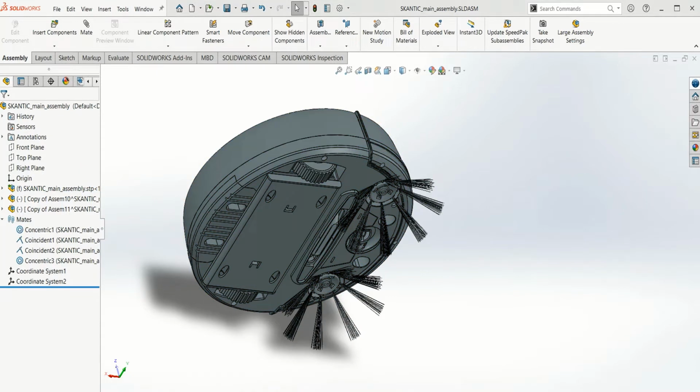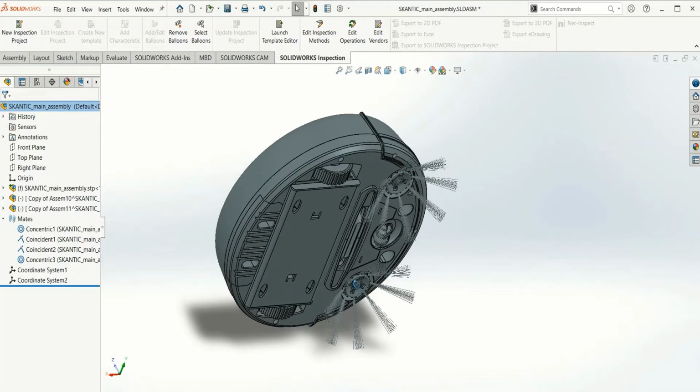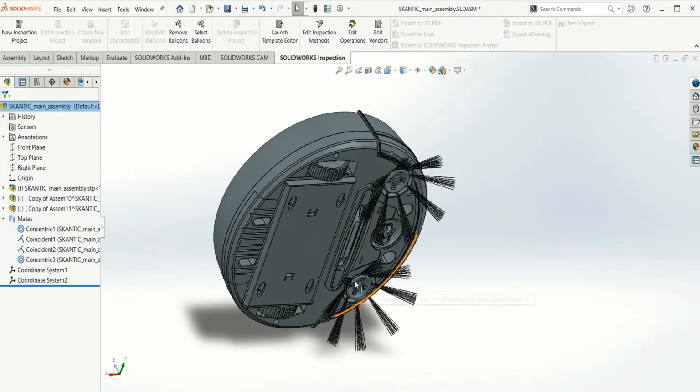For both wheels, a specific coordinate system should be defined, like this. And for doing that, you could use coordinate system in reference geometry in assembly section. After that, mates or constraints should be added between body and each wheel. For this project, concentric and coincident are enough.